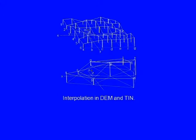Here in the DEM, a point M whose elevation is to be found is located somewhere between 3 and 4 and B and C in the row and column directions respectively. Similarly, in the TIN, this particular point N, whose height is to be estimated, lies within the triangle C, B and E. So, now let us look at how we would do the interpolation.